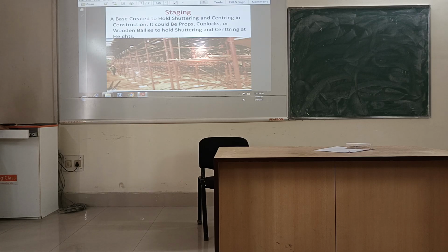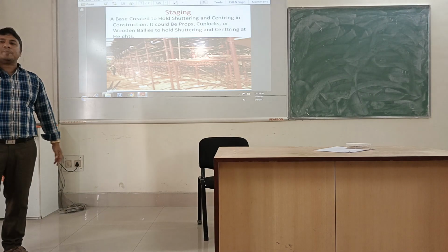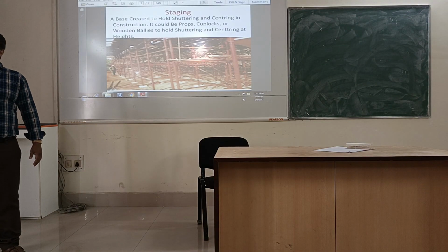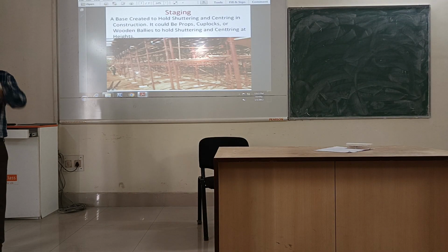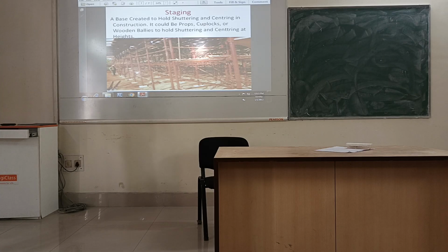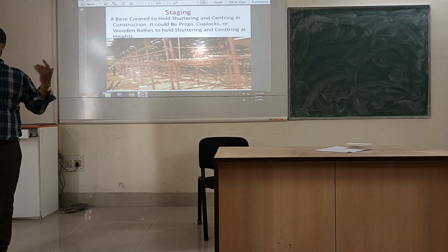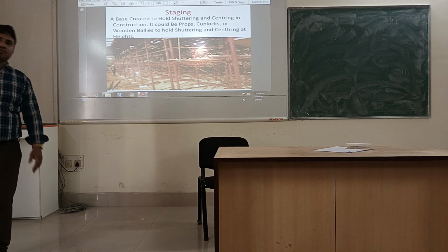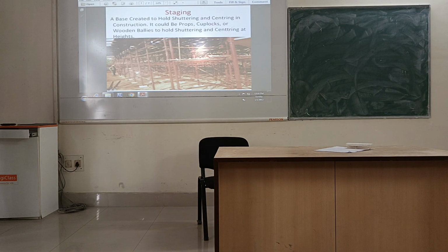Okay. So staging work is actually carrying the load of the structure, where the structure is to be prepared. It is carrying the load of the concrete and steel, that is the steel that is prepared and the concrete that is poured, and also the live load in the form of workers who are coming to the site, and also the engineers. Okay. So these are the common terminologies that you may come across. So the concept must be clear to all.